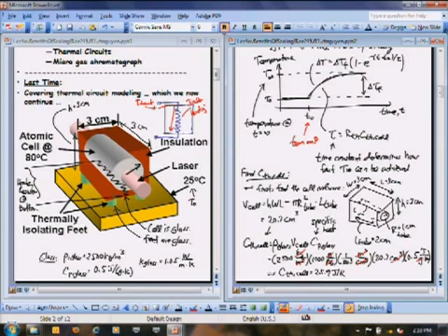That's simple geometry. We did that geometry last time where we took a square box. That's the volume in that square box. We subtract from that the hole that's been cut out of this, a cylindrical hole that contains the gas, and we get a volume of 20.7 cubic centimeters and a thermal capacitance, by just plugging that volume into this expression, of 25.9 joules per Kelvin. Okay, and that's where we left it last time.